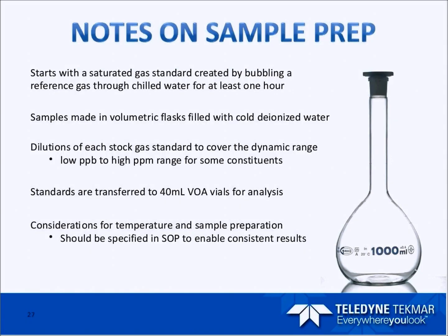And now I'll talk about some of the issues if you're going to do this analysis. These are my tips that I give to people when they ask me questions about this. Since you're starting with the saturated gas standard, as I touched on earlier, you want to keep it cold throughout, pretty much. When you're making the standard, keep it as cold as possible. When you're handling the standards, try to minimize your amount of movements. Try not to let them sit out too long. Try to keep everything as consistent as you can with your sample prep.